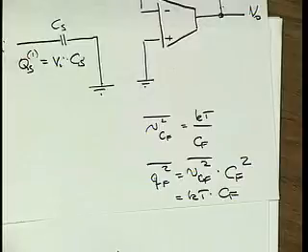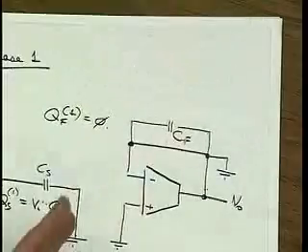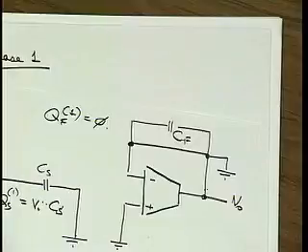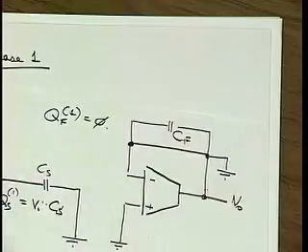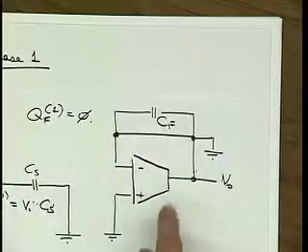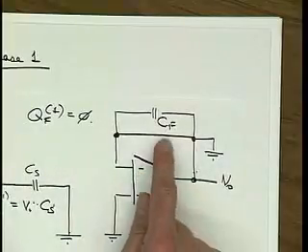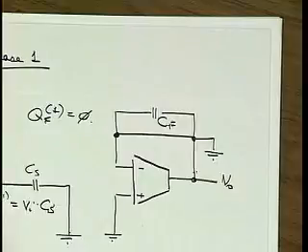So this charge sample amounts to a certain voltage. We don't know its value, we know only its variance. Sometimes we were just lucky and we have 0 volts there, or maybe a femtovolt, something we can't even measure. And sometimes it's going to be a microvolt, and sometimes minus 700 nanovolts, or whatnot. It depends on the size of the capacitor and luck. And during phase 2, that charge is still there, and it's just going to be added to the signal and corrupt the signal.